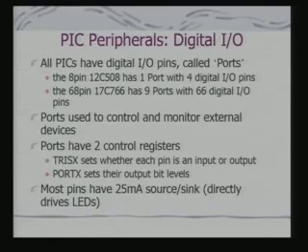And in fact, there are external pins and these pins are associated with registers. So whenever we want to do any manipulation on the port, one of the ways of doing it is to read and write these registers. So ports typically are used to control and monitor external devices, and in fact to read input or write output onto the external devices.